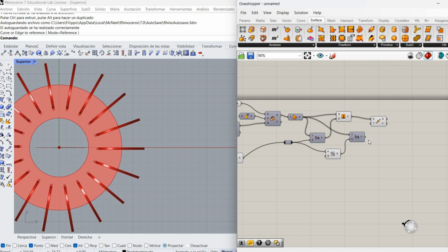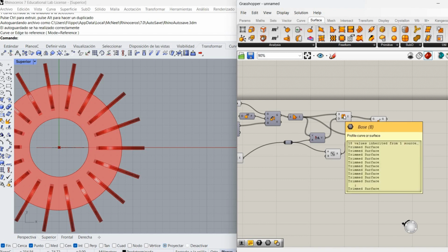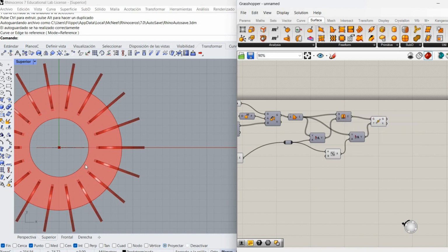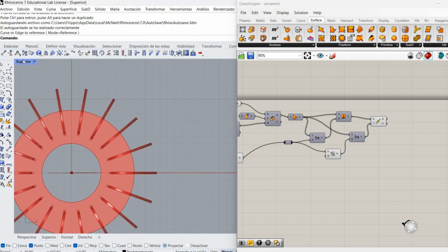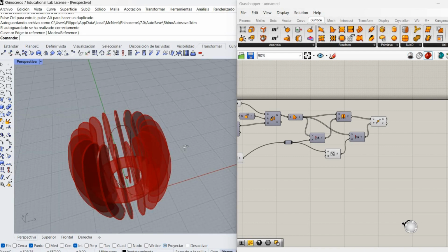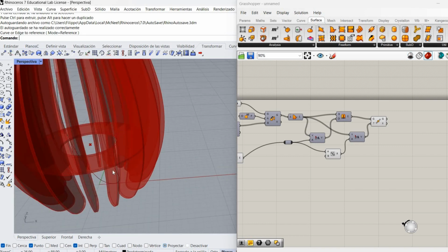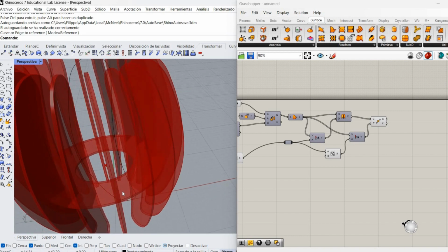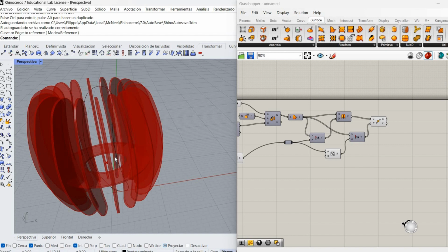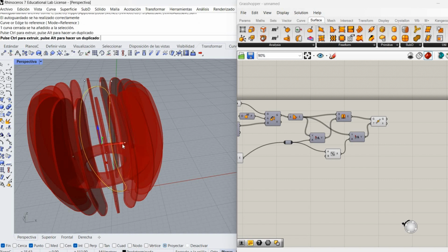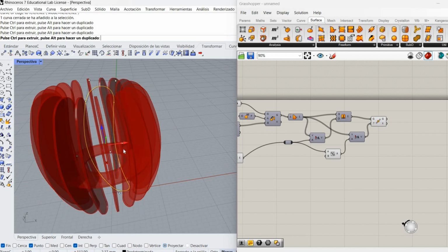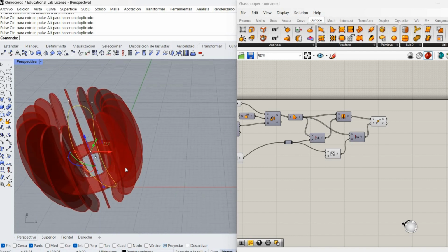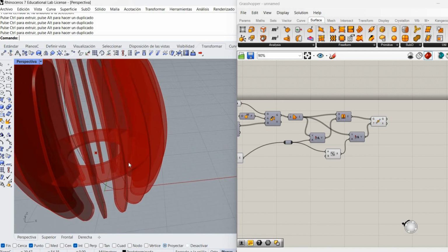That way, I'm just moving those surfaces. I'm not extruding them. I already extruded them before. I'm just moving them half of their thickness to the other side of the extrusion, let's say. Okay, so now I have my two groups or my two volumes, which are the blades and the base. I need to make sure that they are intersected with each other. If I move the position of my curve, then the position of those blades is going to change. So I need to make sure that they are being intersected. But I can play with that if I want.